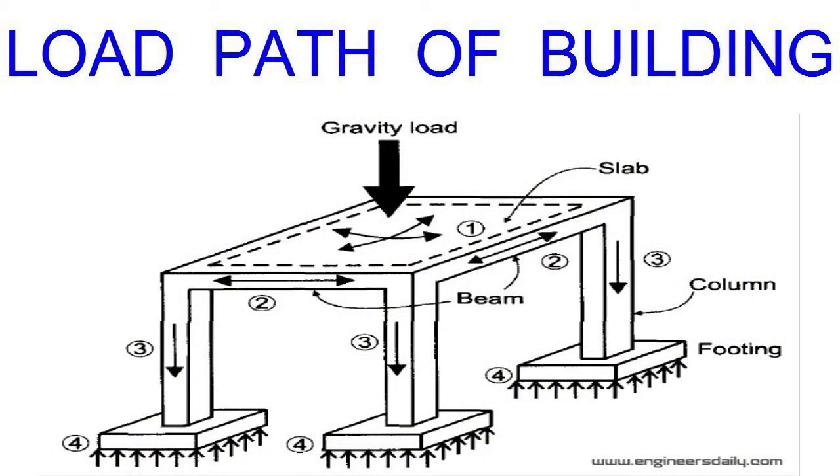Column is also a very important member of any RCC structure because loads of any structure go through slab to the beam, after that column, and through column the total load goes to the substructure.